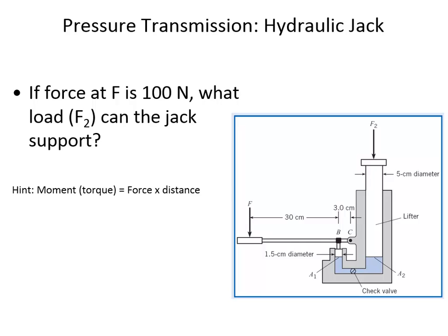Relative to 6 million pascals, go up 1 meter through oil and it's going to be a loss of pressure of maybe like 9,000 out of 6 million. So we don't have to worry in this case about this being a little bit higher. We'll just assume that the pressure here is the same as the pressure there.